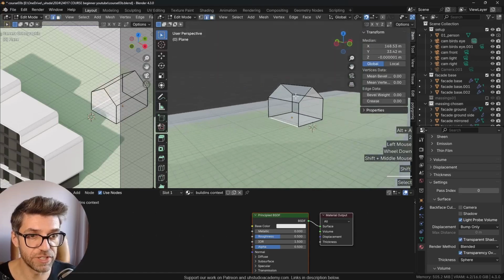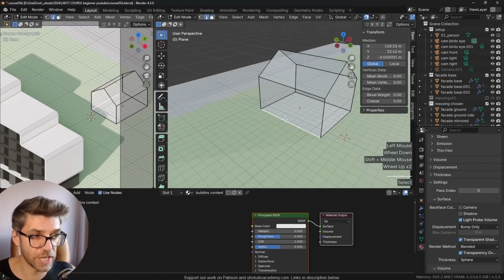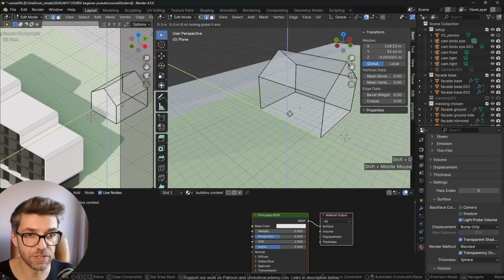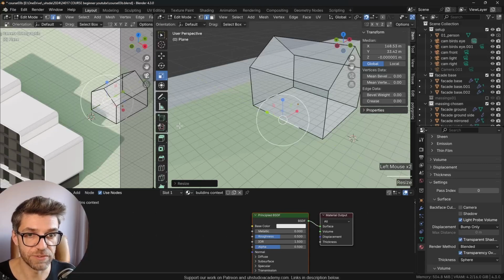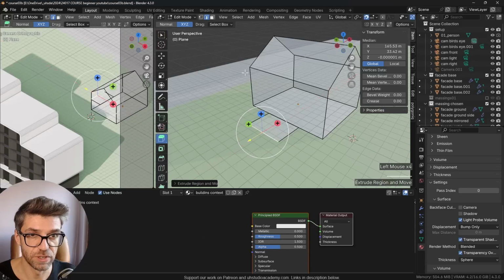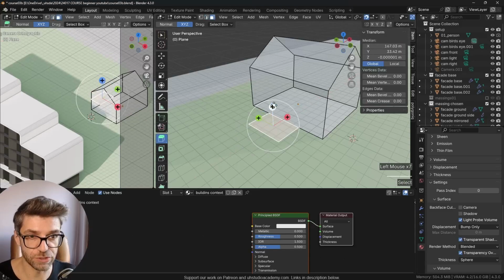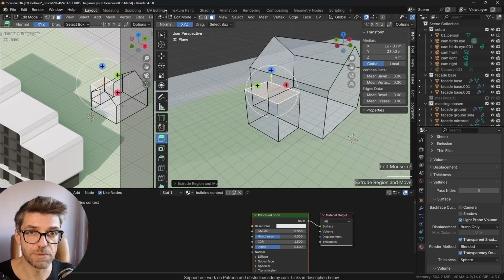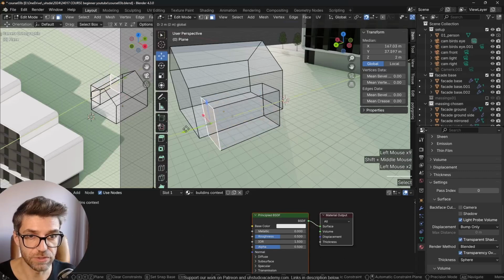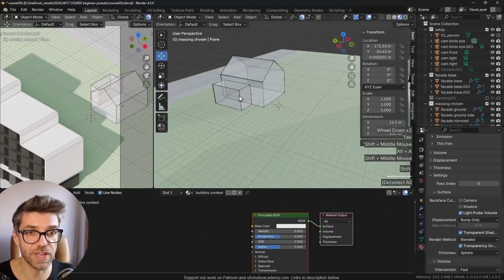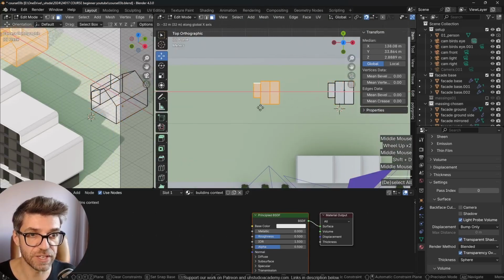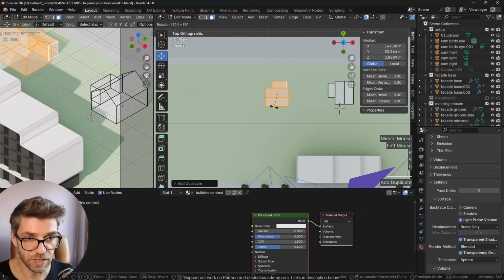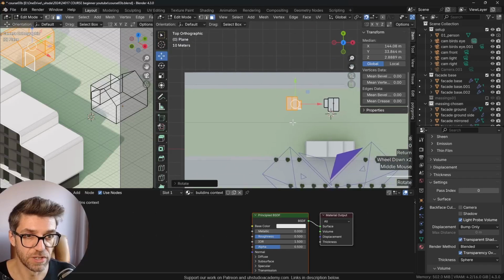Now let's go back into this object, and we're going to do everything within the same object. So let's duplicate something over here, and we're going to scale it. So whatever we have scaled here, extrude it, select the face, and extrude again. And maybe move one of these faces a little. So this face over here, just to show kind of the typical variations that we see in houses. Now let's select everything, go to top view and duplicate this to somewhere over here, maybe rotate it 180 degrees.